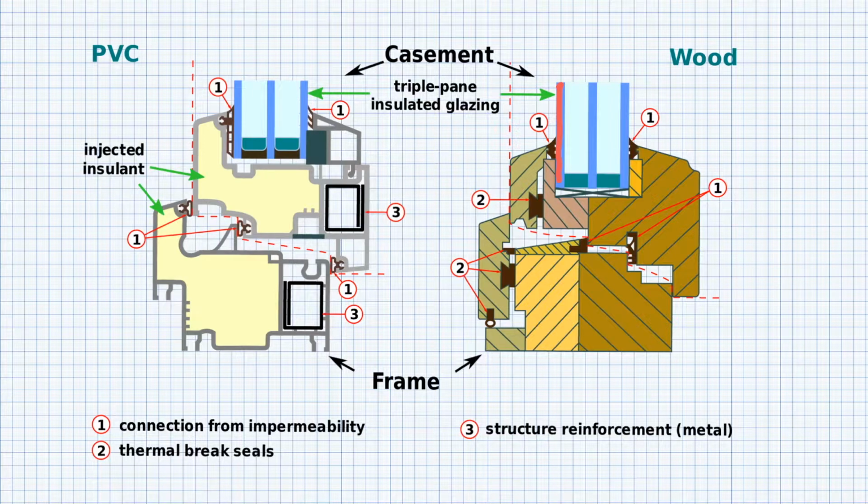The triple paned windows work so well because in between the layers of glass, there are actually these cavities of dead air. That dead air acts as an extremely valuable insulation barrier because the air is not moving around, so there's less volatility, so less thermal energy is able to transfer across through that boundary. So this is one of the ways that glass can really be improved, is by going double or triple pane.